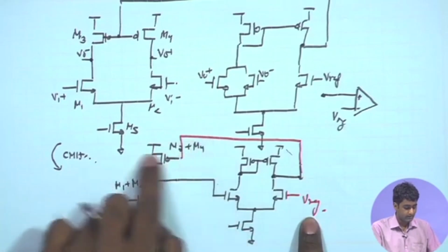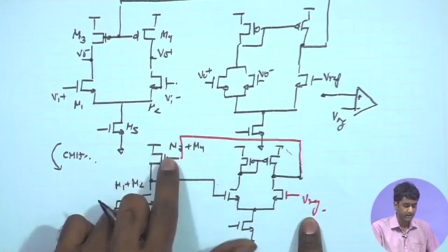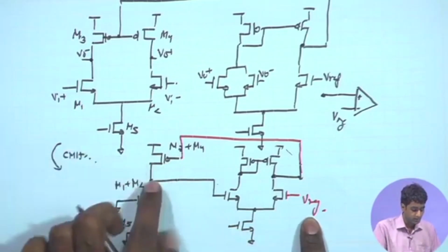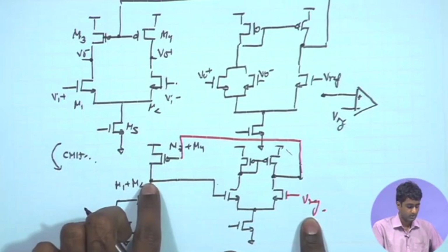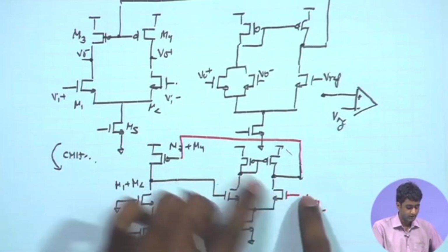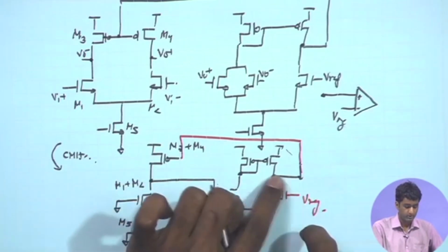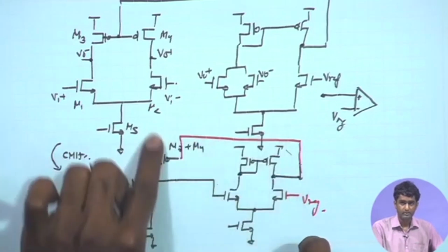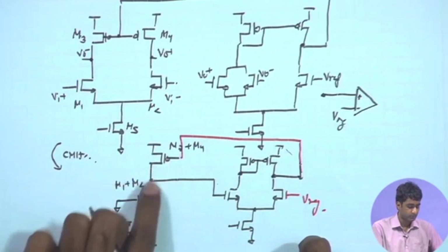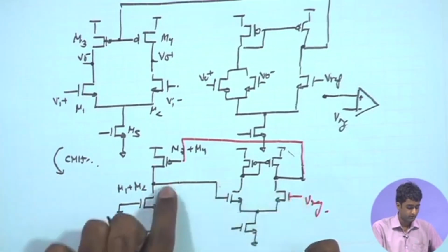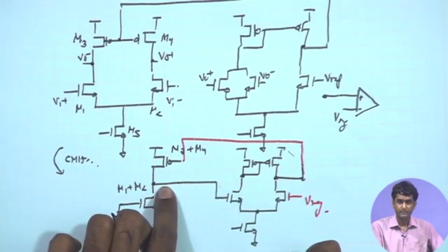But after that you have another inverting stage. So, this is something like a common source stage where M3 plus M4 is acting like the input device, and therefore, we are going to have another inversion over here. So, with respect to Vref, we will get a non-inverting gain till this point. From here to here, one inversion, and then after tracing the loop from M3 M4 gate to the drain, another inversion. Therefore, from Vref to this point, we have a non-inverting gain.